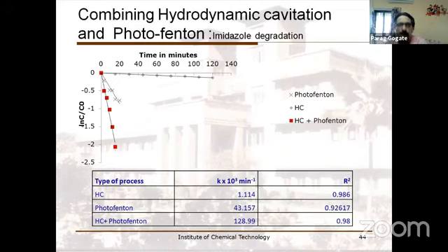If you're talking about a complex system, like a common effluent treatment plant where you want to treat a variety of chemicals present as mixtures. In academic studies, most people would want to work on simulated effluent. You take a compound, you dissolve it, that is your simulated wastewater, and then you get beautiful trends, but they may not be replicated when you talk about real industrial effluent. So that needs to be looked at. Real industrial effluent is a complex system altogether. There are too many compounds present, and the treatment has to be thought about differently. So there, all the combinations are going to be quite useful.